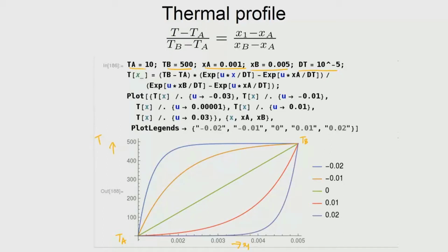So, you could then see that you can have the flow leftwards and flow rightwards, and for both these situations the temperature profile is deviating from the straight line. The straight line is the conduction solution, which we already know, because a straight line is a solution for the conduction equation when we drop all the terms except the diffusion term.